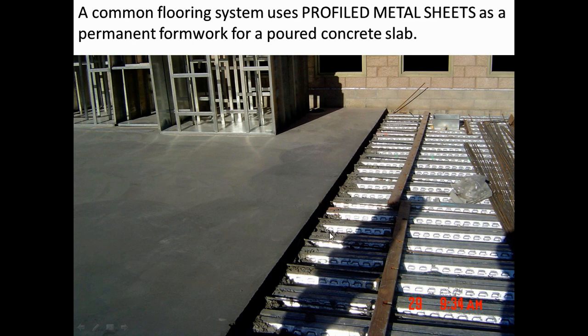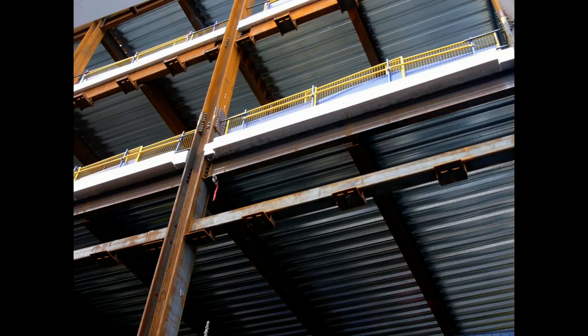But it's also metal, isn't it? So it's taking some of the tensile strength of the floor. This is reinforced concrete. There is some reinforcing. You'll see there's also a little bit of reinforcing going in, so there's some steel rods to integrate with the concrete itself. This is right underneath it, isn't it? But all in all, it acts together, and it's a very common way of pouring concrete slabs. And that's looking at the same thing from the underside. So here's the profile metal sheet.